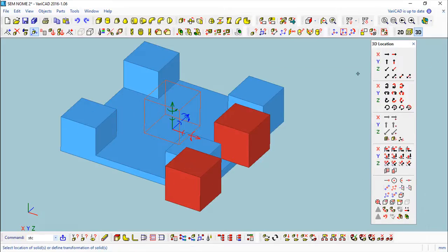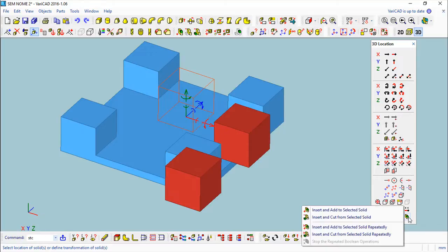Finally, besides these options here, we have also two little options down where we can define, when inserting a solid, constraints and Boolean operands. I will leave the constraints out because we still did not see the constraints. But for example, in the Boolean operation, if you click here when inserting, and the operations, you know them already, we've seen them in one of the previous lessons. As an example, we can insert and add the solid to another one.